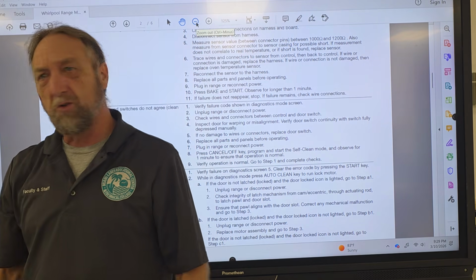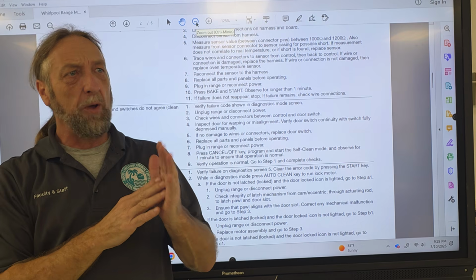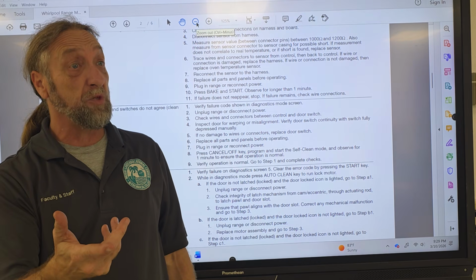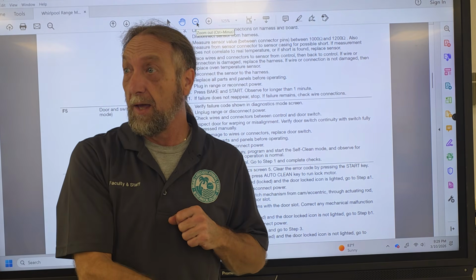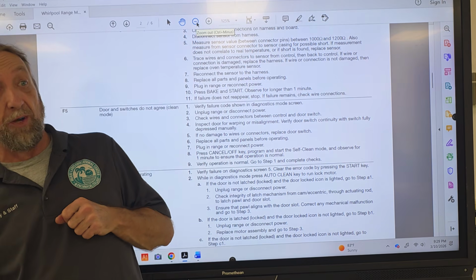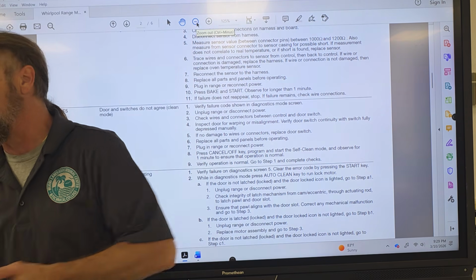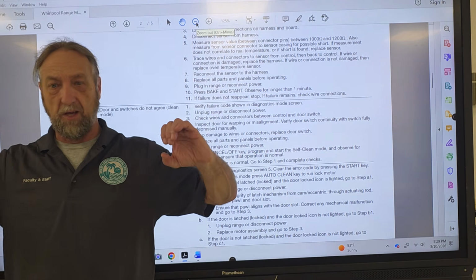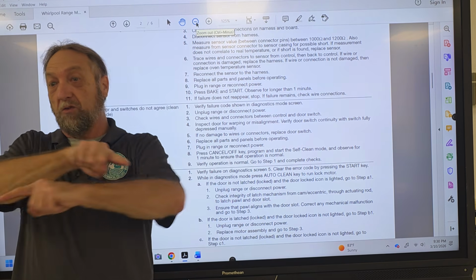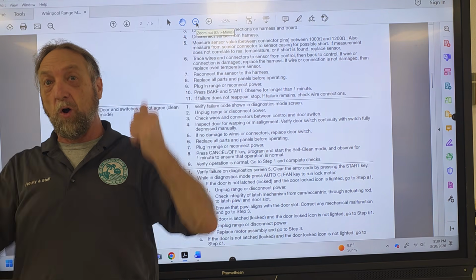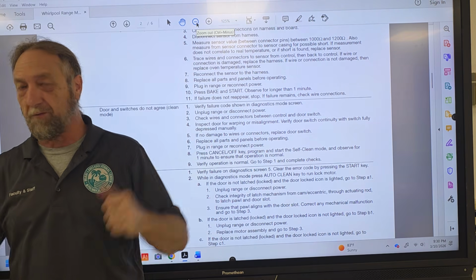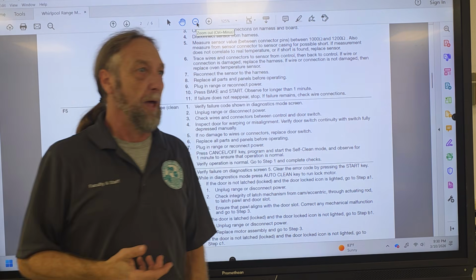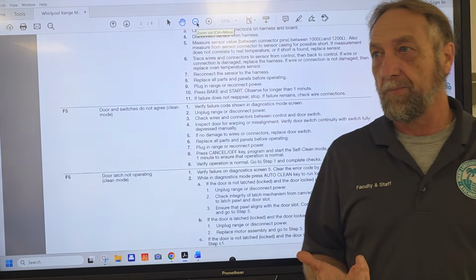Dishwashers too. When you see the hinges bent like that, they wouldn't bend just by the door opening and closing. Now I have seen dishwasher door hinges bend because one of the springs broke, and by accident the customer opened it and thought the spring would hold the door, and the door came down and bent itself because it was so heavy. GE used to have two rollers and a wire that crisscrossed and went to the door, and when you opened it, the springs would stretch the rollers back and forth. That rope would break, and then the door would drop and cause bent hinges. But if the door is not aligned, that would happen.